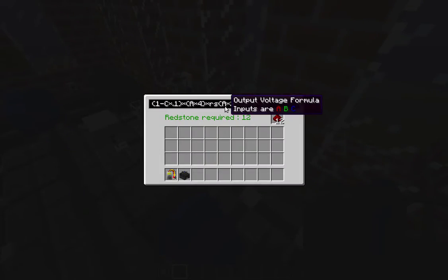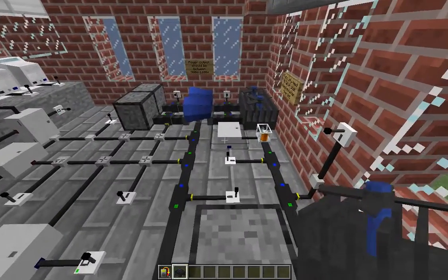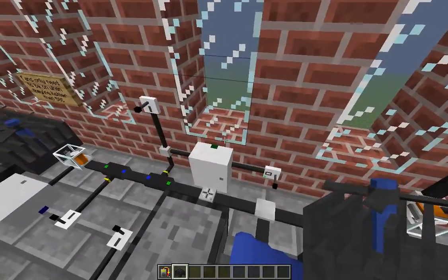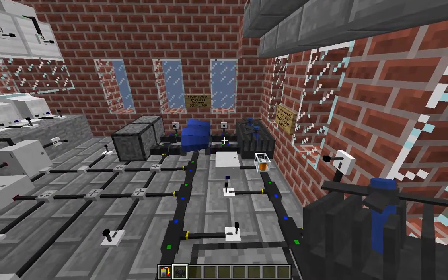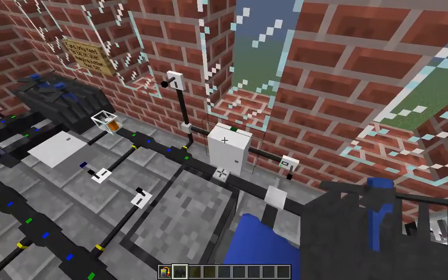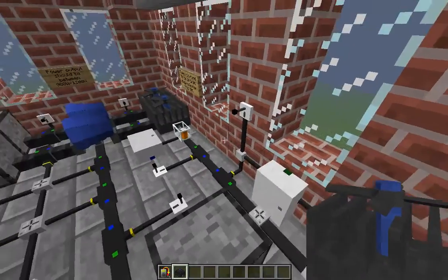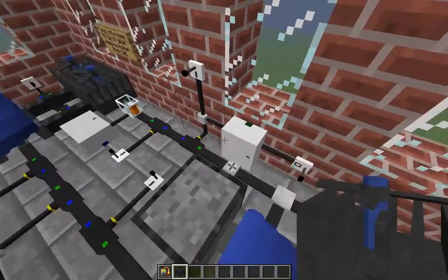Right now, what I say is take A, multiply it by 2. If that's less than 0.4, then turn it off. Otherwise, if A times 2 is greater than 0.5, turn it on. This equation part right here is actually identical to the one right here. The only reason he's multiplied by 2 is because that thermal probe reads from 0 to 200, and that one reads from 0 to 100. So he's going to turn on and off in sync with the opening and closing of that gate.